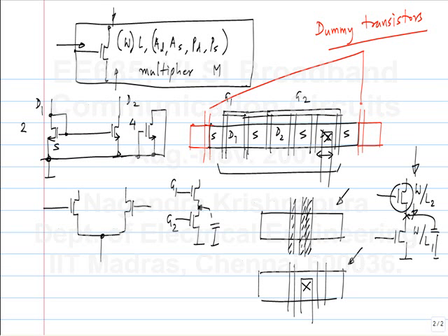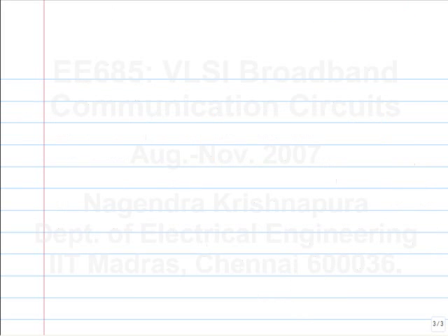So it's easy to delay such signals and add and so on. You basically can do the delaying with a flip-flop, and that's what we use to construct a linear equalizer on the transmitter side. Now we will see what to do on the receiver side. In general, the receiver in any system is more complicated than the transmitter, because we've already screwed up the signal. Now you have to enhance it somehow and correct the signal. So the receiver generally turns out to be more complicated compared to the transmitter.